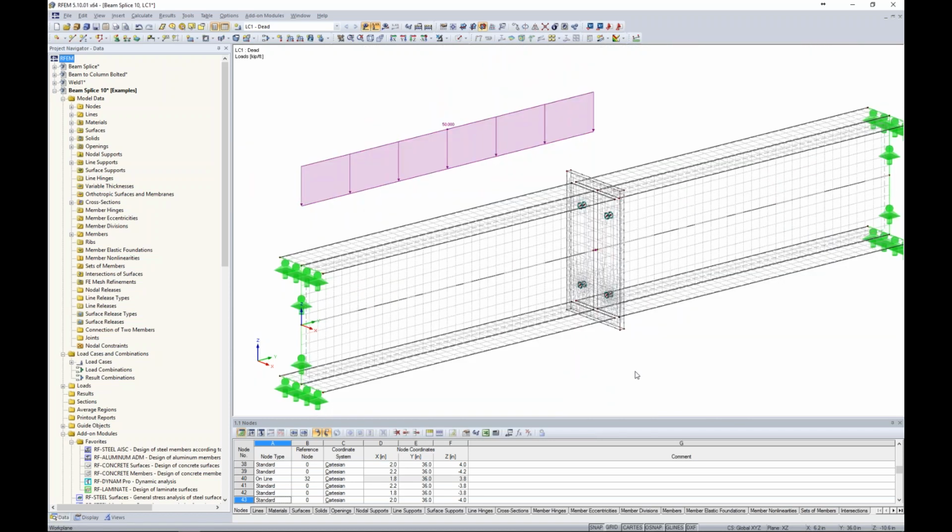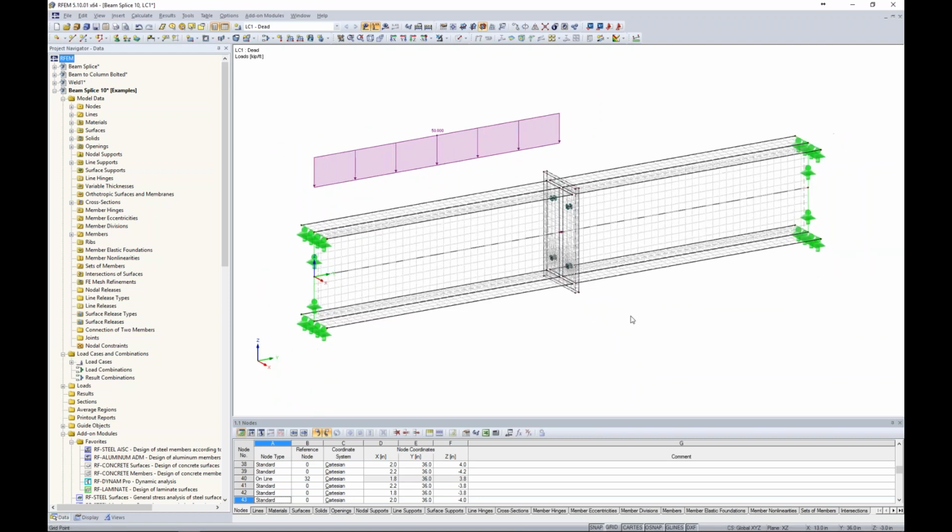Now there is an iterative process with this. You can continue decreasing your FE mesh size smaller and smaller and smaller, and sure, your results are only going to be more accurate. But at some certain time, you're going to be increasing your solution time to be very high in comparison to how much your results are actually changing. So you'll get a better feel for this as you begin to model in finite element software more and more.